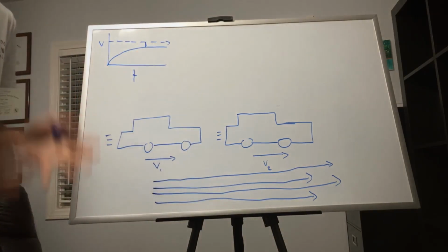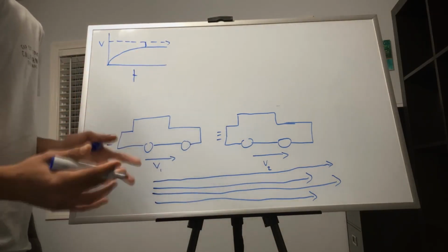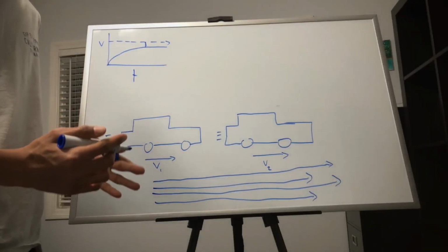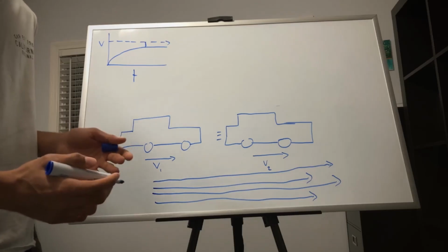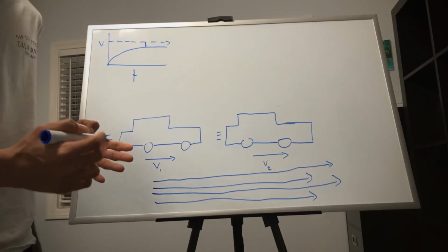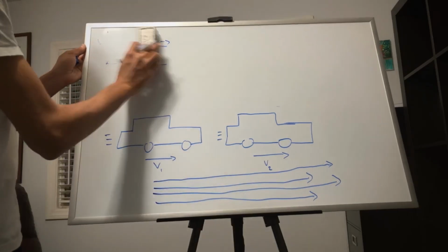So the solution to this is to use a proportional integral derivative controller, where we add the integral term. This integral term will affect our overall output by basically summing up our past error. So if I just erase this graph real quick.